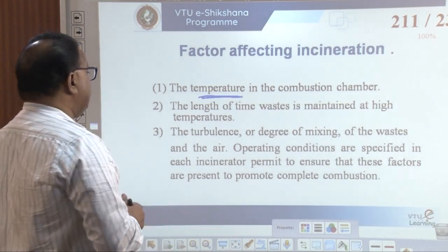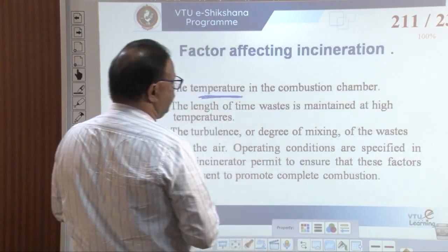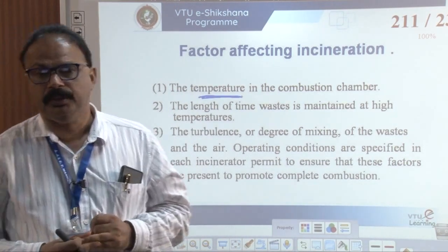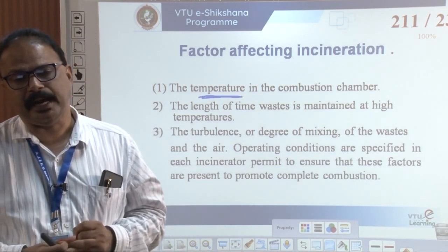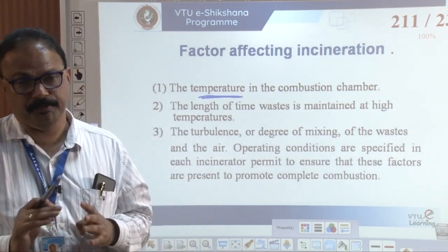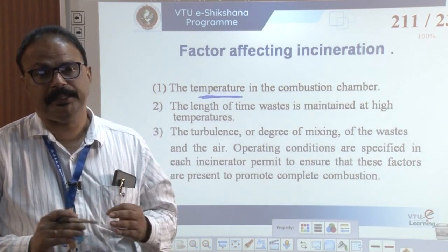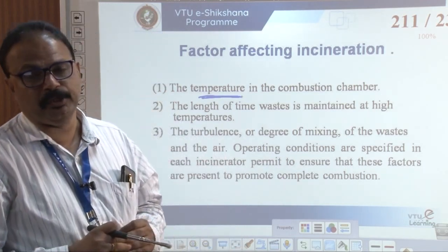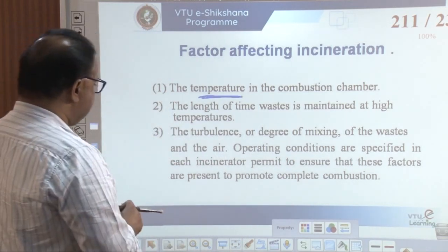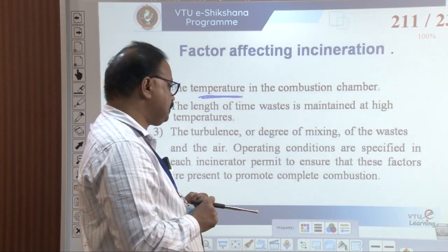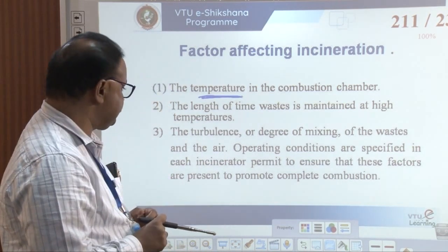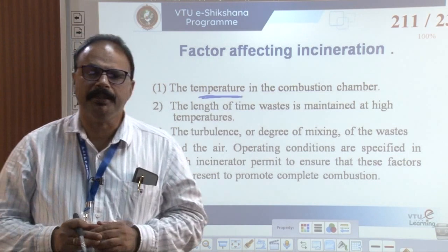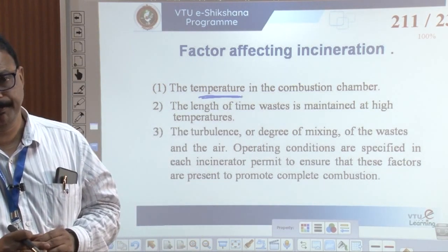Second one, length of the time waste is maintained at high temperature. Time should not be wasted. It is maintained at a high temperature. Third one, degree of mixing of waste and the air. Operating conditions are specified in each incinerator permit to ensure that these factors are present to promote complete combustion. This is very, very important.